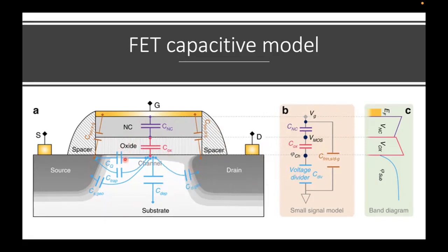As I just mentioned, the dominating capacitance here is the depletion capacitance, because simply this is the most dominating capacitance across these capacitances in blue. And finally, these two capacitances can couple together to have one capacitance, as you can see. So this can simply be the capacitance model for a MOSFET.